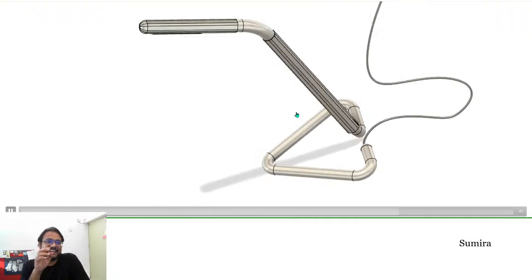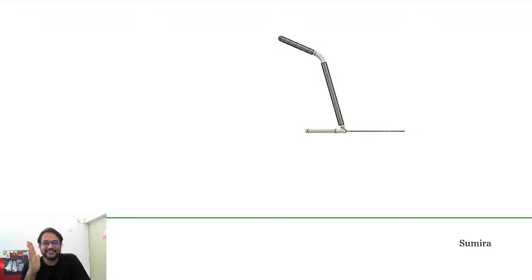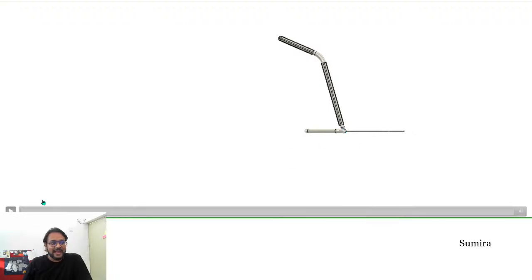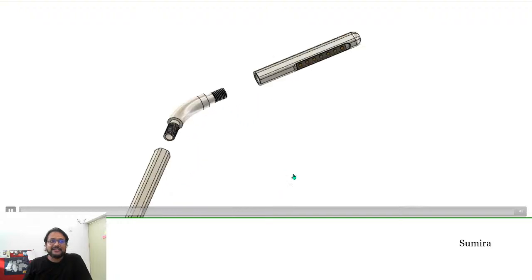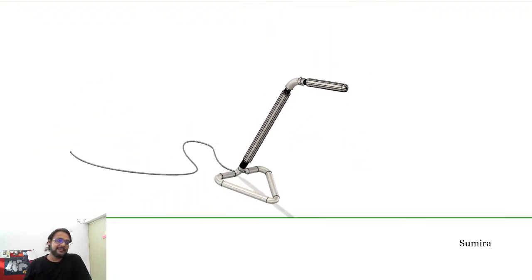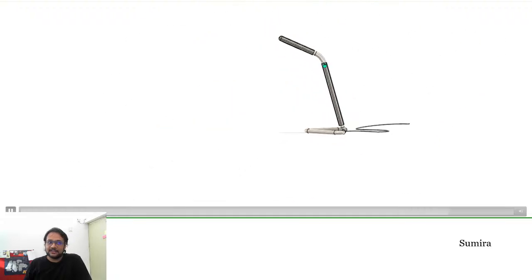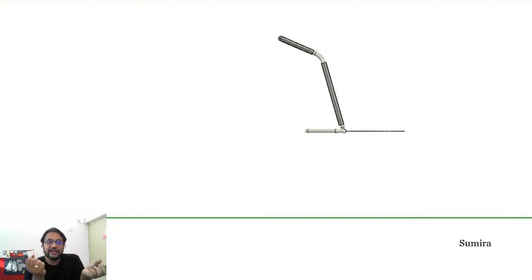However, there's always going to be a however, because nothing is perfect, right? As you can see, the bottom of this is a bent piece of material, and if you consider it as thick as the hexagonal rod, this is a very thick piece of material. Bending this would be a tremendous effort. So it's not a good idea to bend something this thick, unless it's totally unavoidable. And besides that, bending was not really a machining operation that we discussed.